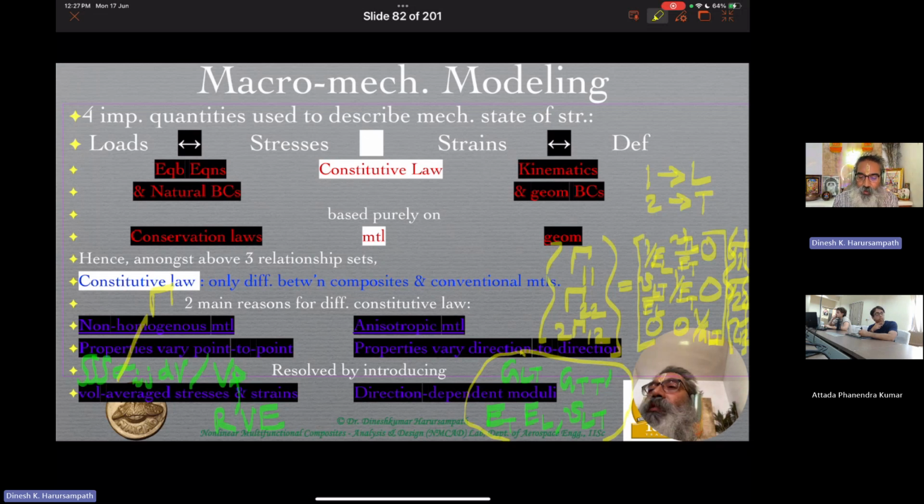So once we know this, of course, we already know that because these three gammas are known, we can get the gamma I3 as a function of these gamma alpha betas, and from which we know all the gammas, and the displacement fields are defined in terms of that. So we can go about trying to determine that as well. Okay, so we know the compatibility has to be satisfied, because of which the six cannot be given independently, but because we have made the plane stress assumption, that will be violated. And that is one of the issues that is there with this whole methodology.